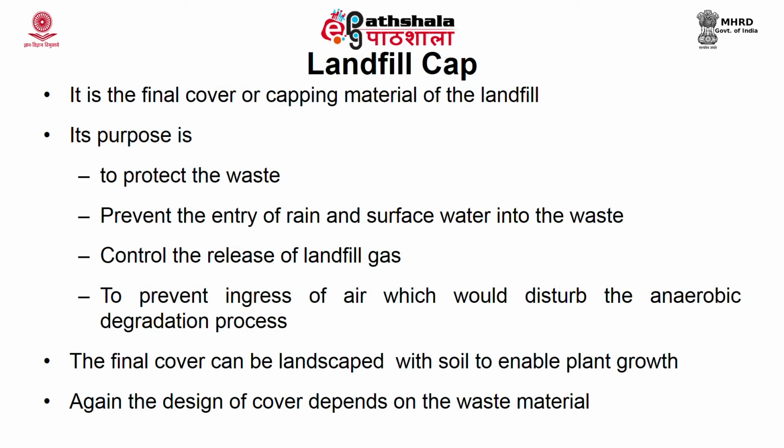Now, the final cover can be landscaped with soil so that you can have vegetation or plant growth. Again, the plant growth should not be deep rooted plants; some superficially rooted plants can be used, even grasses can be grown. This is just as a part of beautification. Again, the design of a cover will depend upon the type of waste material which is being loaded or deposited into the landfill.